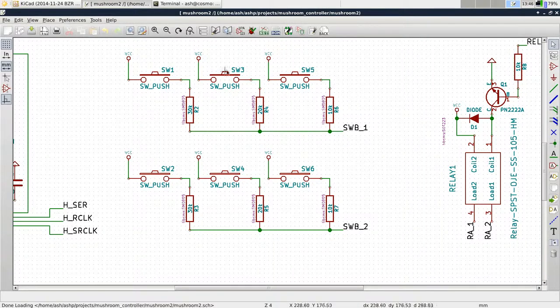So in the case of this switch block, you've got the VCC, which is a label to say that that's the voltage source, in this case 5 volts, but effectively that can be any label. I could have labelled that 5 volt power supply, because what the schematic editor does is create what's called nets, and nets are connected elements.